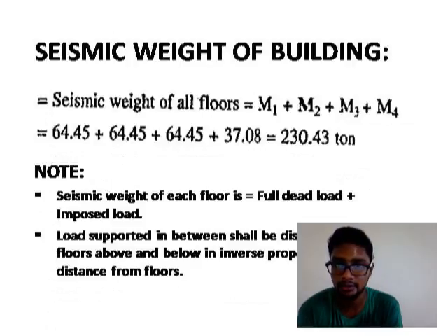The entire seismic weight of the building is M1, the addition of all these masses, which comes to 230 ton. As I said, the seismic weight of each floor is equal to full dead load plus imposed load, and the imposed load is not considered at the roof level.